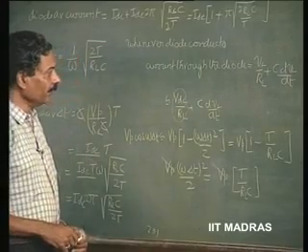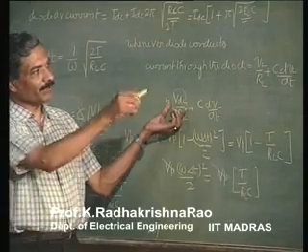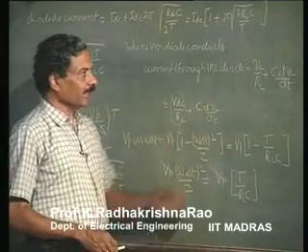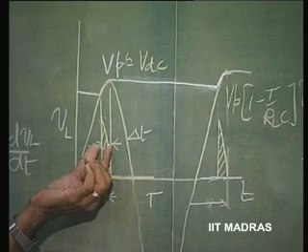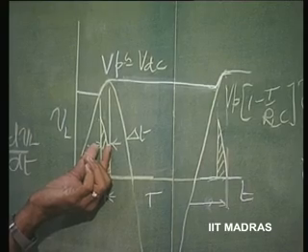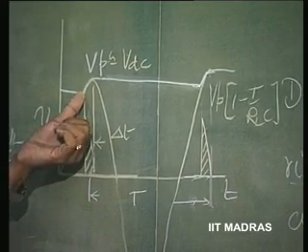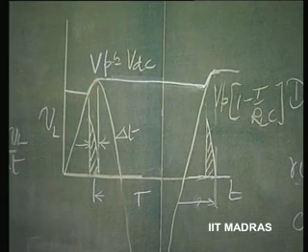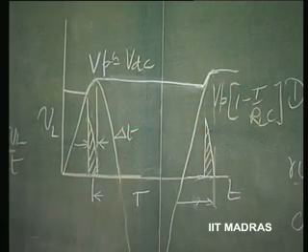How do we get the value of this? This is already known to us. This is given as 10 milliampere for the problem. How do we find out this value? This is done by again approximation, valid approximation. This interval of time is very small. That is how we have done our design. During this interval of time, we would like to know what the voltage at this point is, where it is joining the input. So, at that point of time the voltage is V p into 1 minus T by R L C, that is known to us.